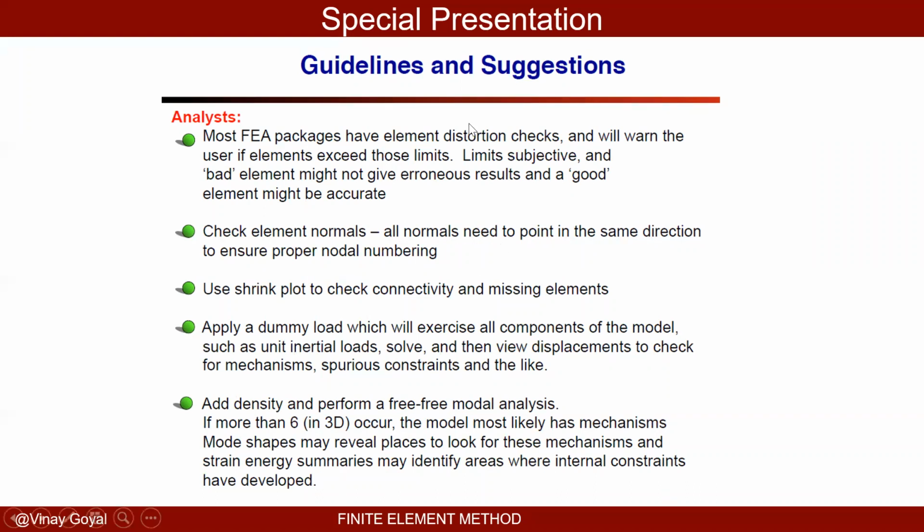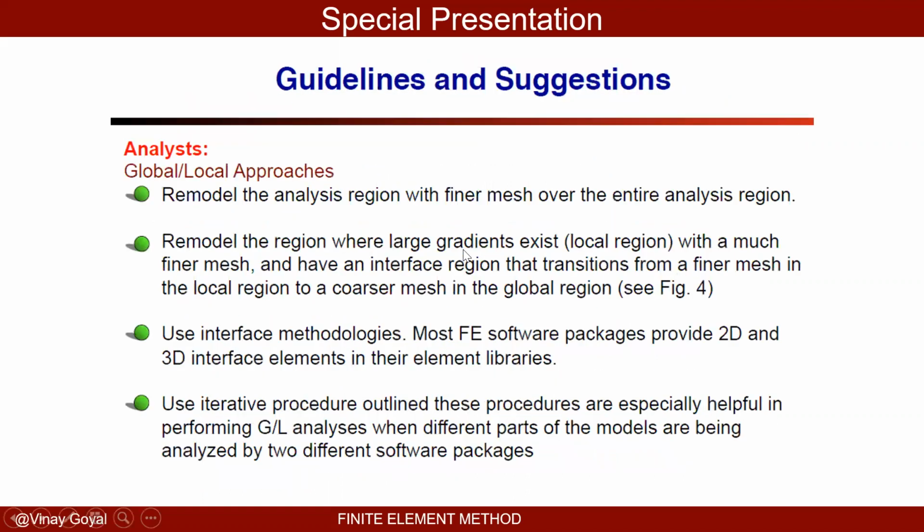Now, in two dimensions, you will have three rigid body motions. The rigid body motions are translation along x, y, and a rotation. Those are the three rigid body motions in two dimensions. In three dimensions, there are six: three translations and three rotations about the three axes. Now, when you do a free analysis, I'll tell you a story at this time.